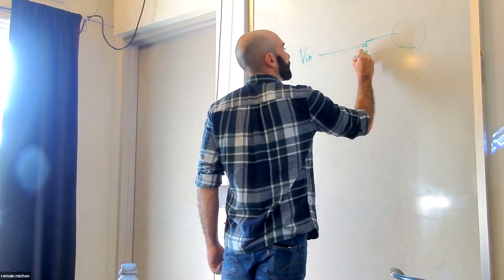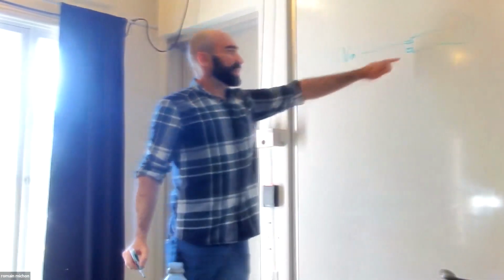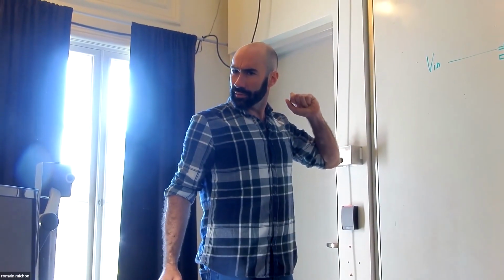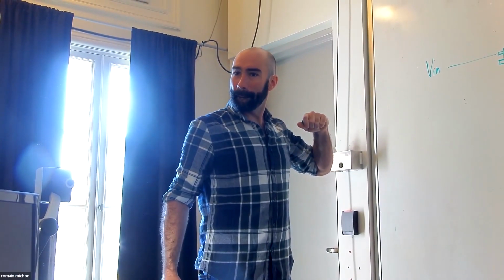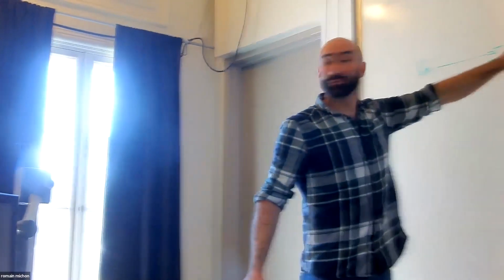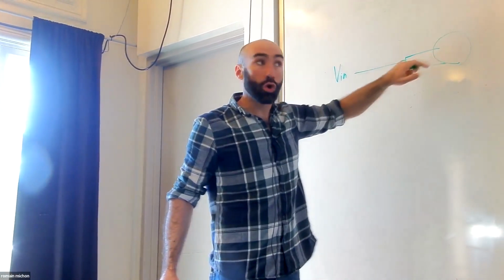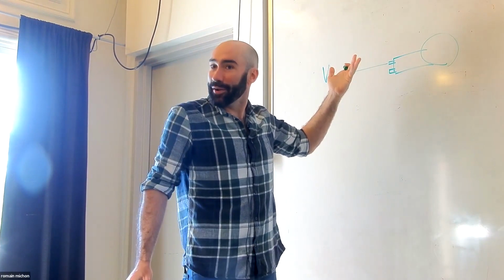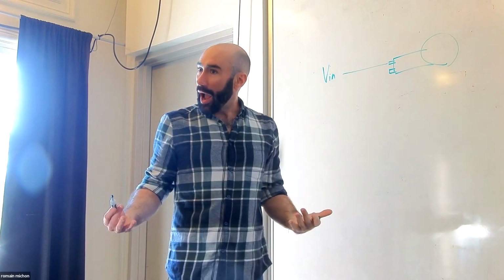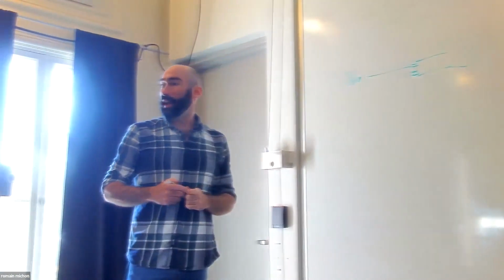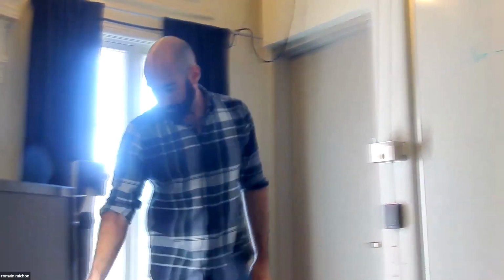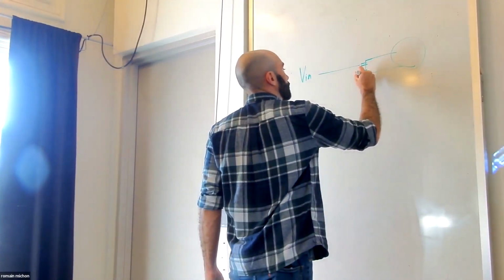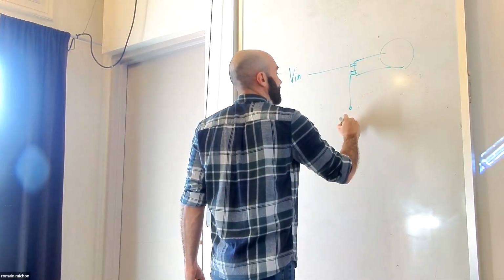And then the other pin is going to be connected, do you know to what? Well, we want to measure what's going to come out of this. So how do we measure analog things on the Teensy? A0, or A whatever. So basically, this is going to be connected to potentially A0.